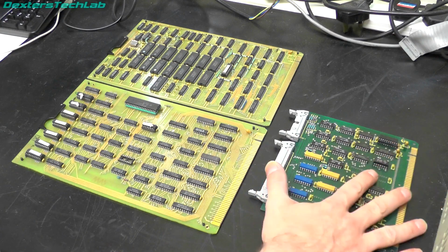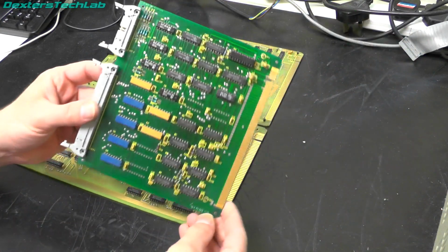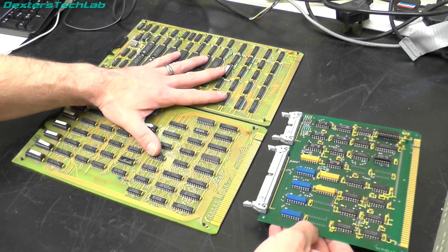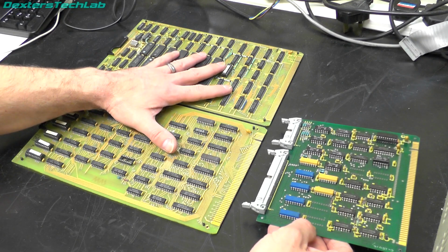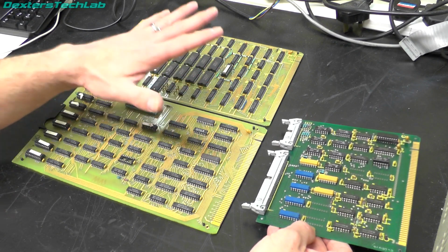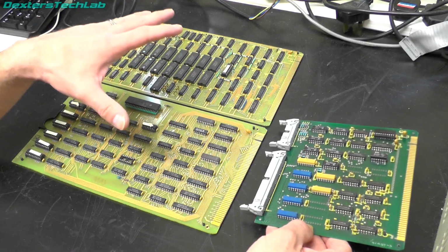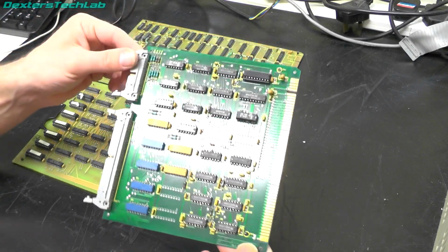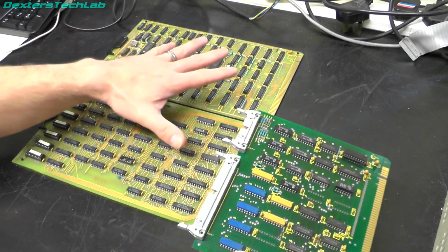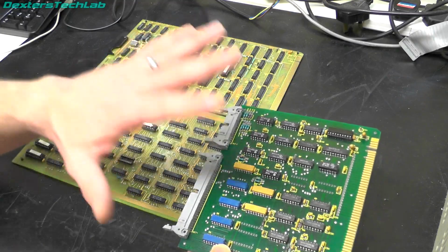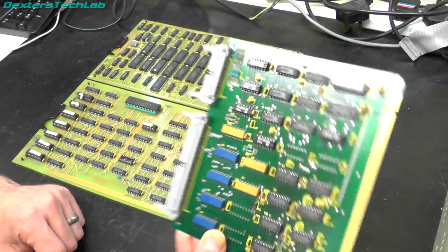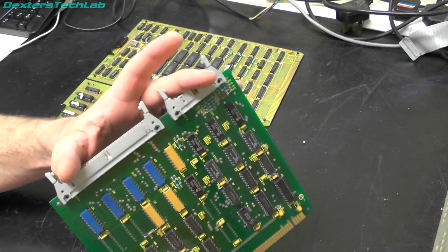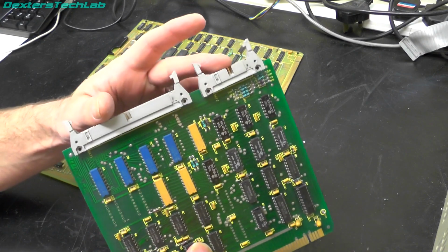Now, just so we can get this card out of the way, this is the SMD interface card. These 2 cards here work at TTL level, so it's all 5-volt signalling. That's all fine, but the SMD interface is ECL. So this card is one that plugs in around the back of the machine, and this converts the signals that come out of these 2 cards from TTL into ECL. That's all it does. It's totally passive. So this just plugs in here, takes the signals from the card edge and outputs to the actual cables that go to the drives.